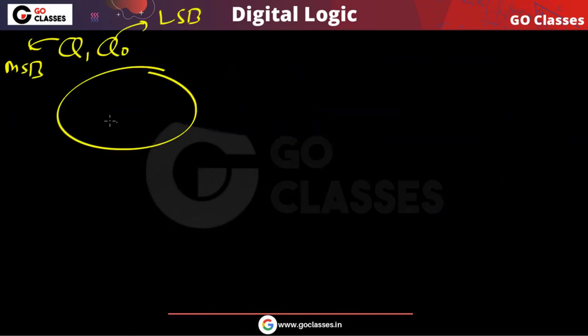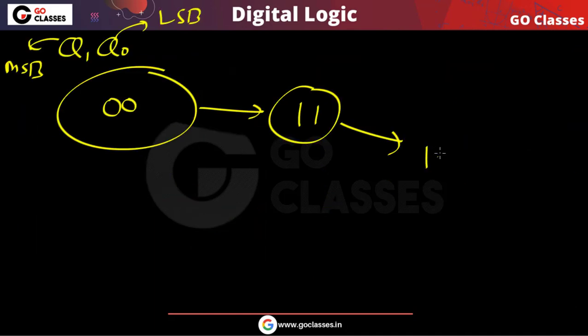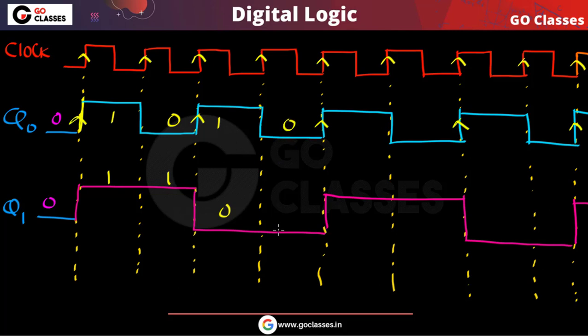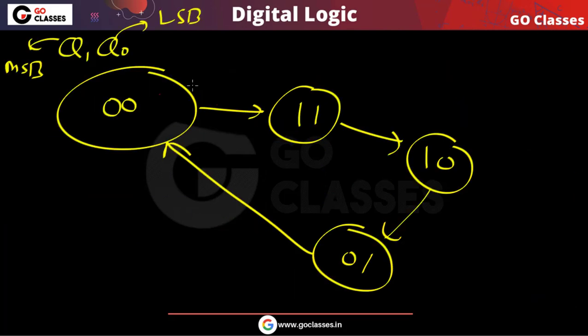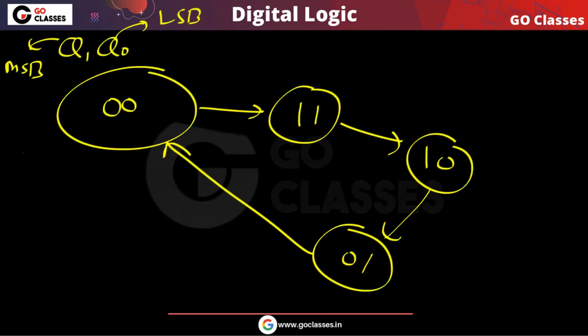Then you can notice that from state 0 0 we are going to state 1 1, and from state 1 1 we are going to 1 0, because Q1 is MSB and Q0 is LSB. Then from 1 0 we are going to 0 1, and from 0 1 the next state is 0 0. Then from 0 0 again we go to 1 1, then 1 0, then 0 1, and then again 0 0. This is the state sequence through which the counter is going.